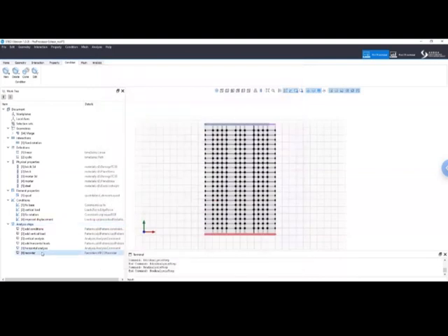Perfect. Now we need to do something here. I need to put the recorder just before the horizontal analysis. Otherwise, this recorder will never be called. Now, if I place the recorder here, my recorder will only record the horizontal analysis. If you also want to include the vertical one, you need to move it up before the vertical analysis. Now, for the end of this example, we just need the output for the horizontal analysis, so here it is fine. So let me save it.